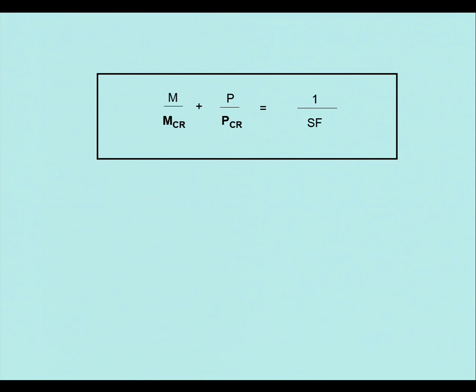So how do we combine the two? M is your allowable bending moment. So if I've got a pressure, water depth pressure, that's not going to change. If I'm going to lay it into that water depth, that pressure's there, I can't take it away. The only thing I can do is limit the amount of bending.